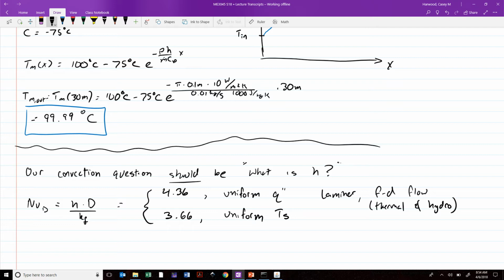Sorry, these are friction factor. These 3 equations right here are all valid choices for computing the Nusselt number in fully developed turbulent flow. Some of them apply for different ranges. So the idea here is take your problem, compute the Prandtl number, figure out your Reynolds number, and look at the right-hand column over here and find the case that most closely matches what you're looking at. And bingo, you've got the correlation to use for your Nusselt number or your friction factor, if that's what's important.